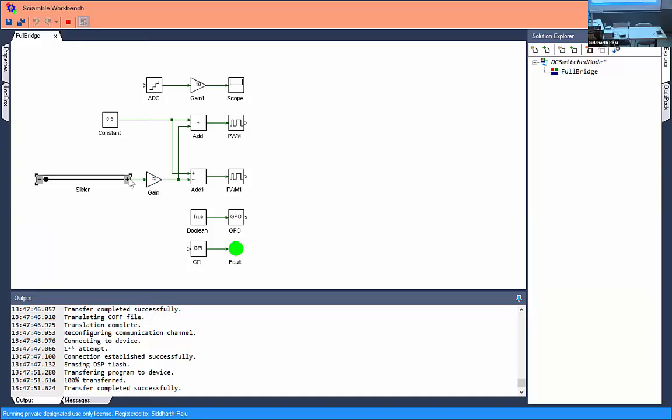So we should see it flicker because it's at 15 hertz right now. Anybody still seeing it flicker? Somebody in the front, Donovan, do you see it flicker? No. Anybody want to give me a reason as to why we don't see it flicker? Would it be like the incandescent light stays illuminated a little bit even after it's off? Because of heat. Inertia? Perfect. Thermal inertia.